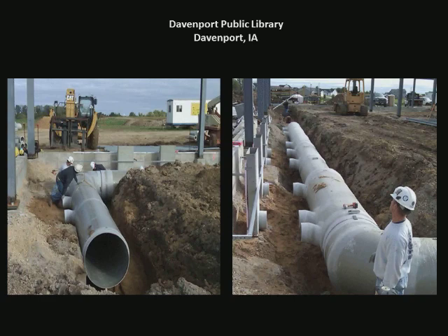Now, depending on how far away the trunk line is from the boot, such as in this example, we would provide a short piece of duct to run between these two, and then the fiberglass wet layup joint would be completed on either end of it. But the boot shows up as one single piece, and then once the slab is poured, the contractor can come along, cut off the excess height of the boot, and install this register group on top of it.